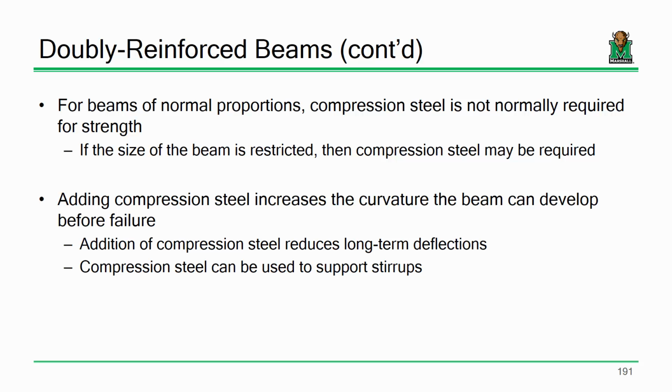You think this would be longer? It would just kind of stretch over time, wouldn't it? It's a material phenomenon associated with chewing gum, okay? Concrete's the same way. Maybe not as drastic or dramatic as something like that, but in the end, over time, concrete will deform under constant load, okay? That's called creep.